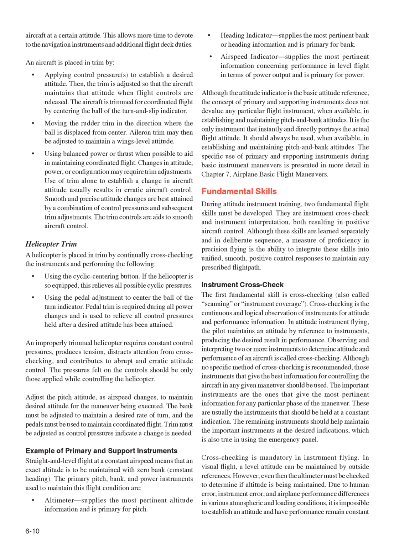Airplane Basic Flight Maneuvers. Fundamental skills during attitude instrument training: 2 fundamental flight skills must be developed. They are instrument crosscheck and instrument interpretation, both resulting in positive aircraft control. Although these skills are learned separately and in deliberate sequence, a measure of proficiency in precision flying is the ability to integrate these skills into unified, smooth, positive control responses to maintain any prescribed flight path.